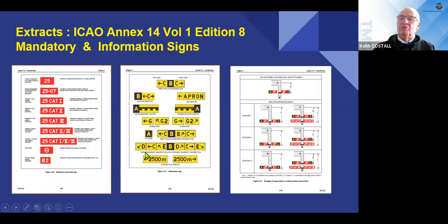So if I'm coming off the runway and traveling onto a taxiway, I'm going to be entering Taxiway Alpha. And that's a runway vacated sign. So I clearly know I'm leaving the runway incursion location and moving onto a taxiway. And I'm being told I'm moving onto Taxiway Alpha.